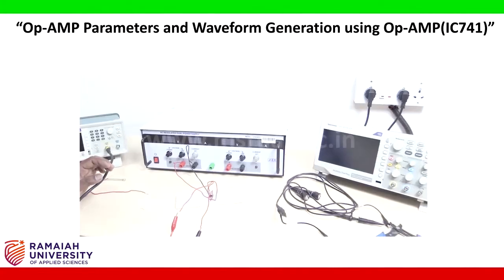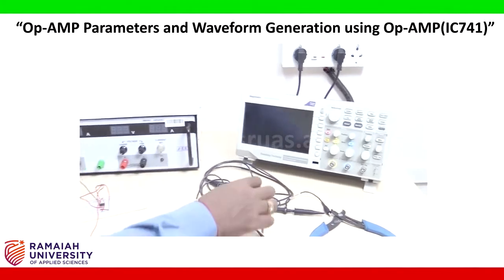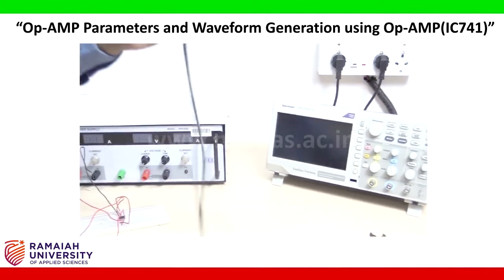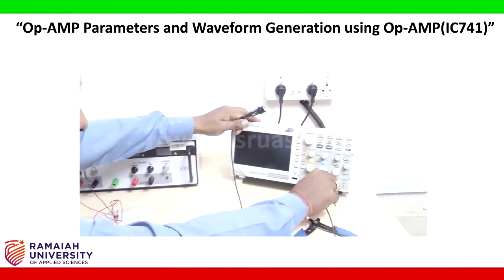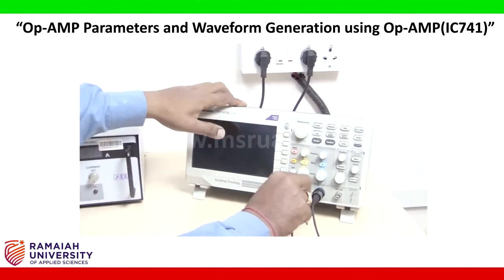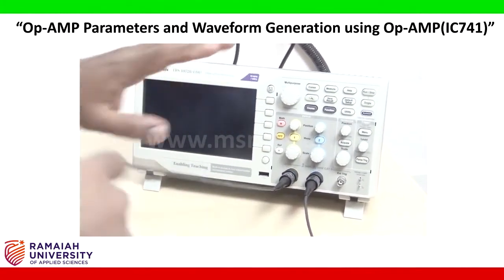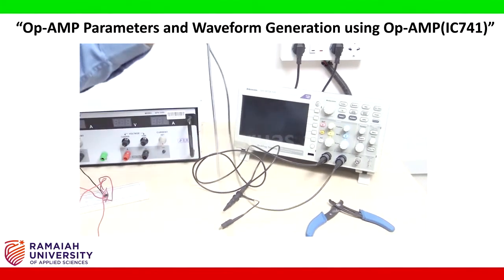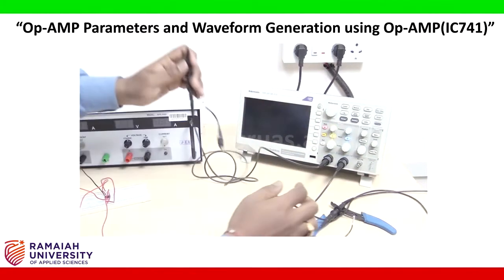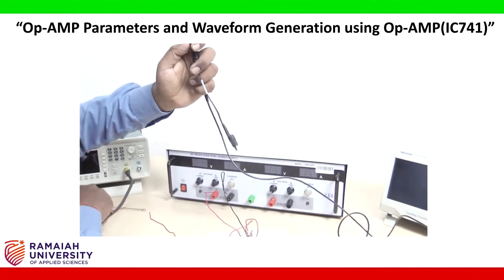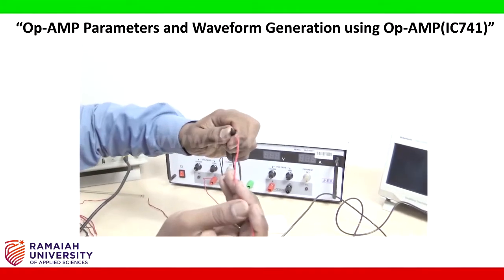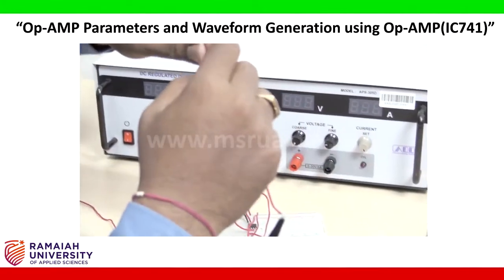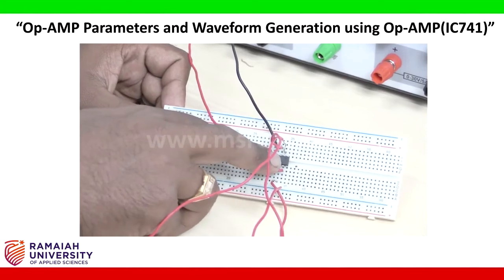To measure the output, I am going to use the digital oscilloscope. I have to connect the digital oscilloscope by using 2 wires for each terminal, 1 wire. So I connect this one to here and this terminal to here. One is used to measure the input voltage and another one is used to measure the output voltage. So now I am going to connect the circuit to measure the input voltage by using this terminal like this. Okay, I connect the positive of the wire to pin number 3 here.